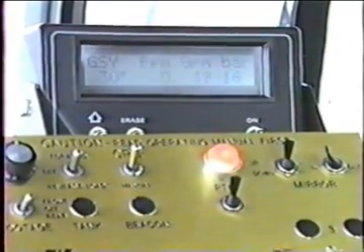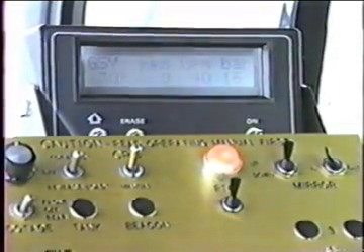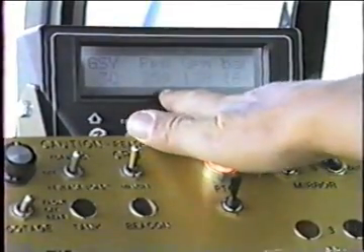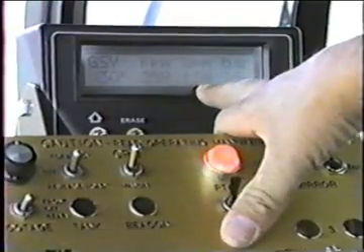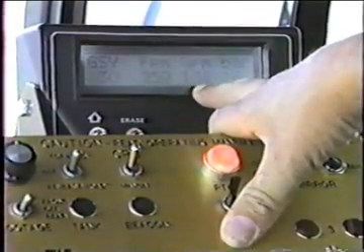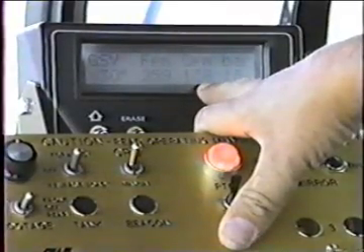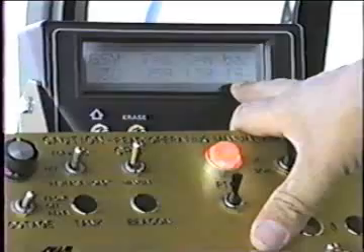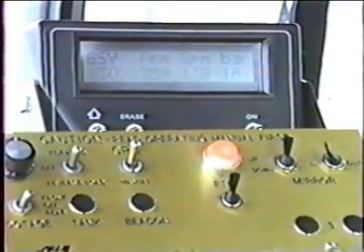We have the spray bar set. Now as we start the truck out and turn on the spray, immediately you see we have driven to 259 feet a minute. The pump has come up to whatever number is exactly necessary to satisfy that. It's calculated out that it needs 138 gallons a minute in order to create 3/10 of a gallon to the yard, 16 feet wide at 259 feet a minute.